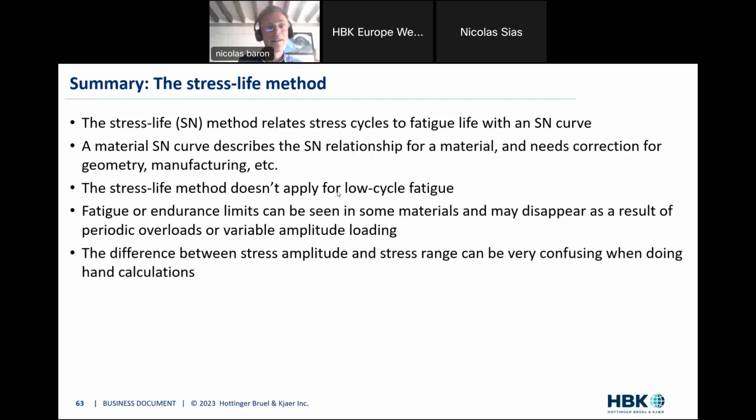So, the thing is that whether we're considering SN, what we've seen so far, or EN, we don't use the same value. In one case, we use the range, that's for the stress life, and in the other case, for the EN methodology, we will use the stress amplitude. So in case you would be doing calculations by hand with Excel, or with some spreadsheet tool, be very, very, very cautious not to mix stress amplitude or stress range. Otherwise, your fatigue results might be totally wrong.